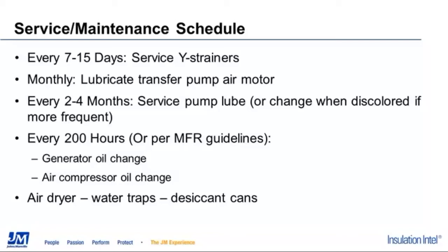Looking at the pump lube, we'll have a picture of that coming up momentarily as well, but on the pump lube, we want to be changing that pump lube. This is a little mayonnaise-looking jar that's on the A side of the machine. That material is initially just as clear as water. It's a bit thicker than water, but not very thick at all.